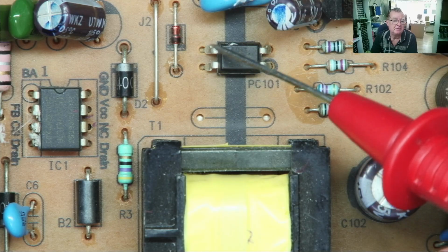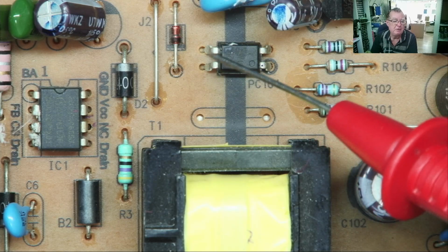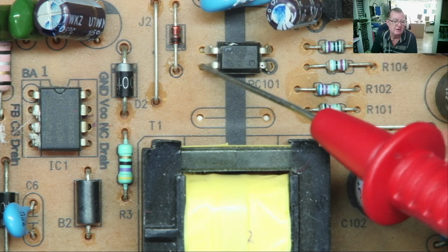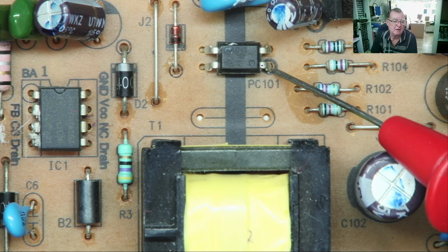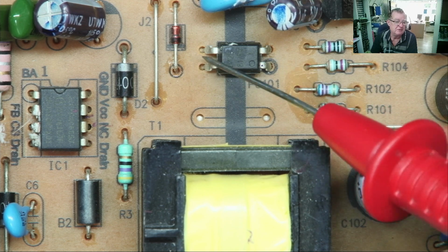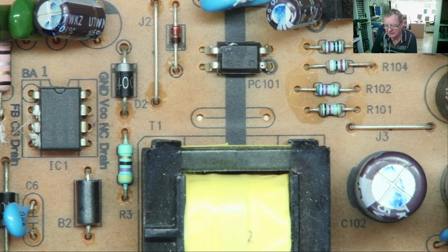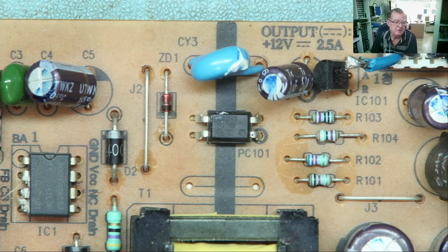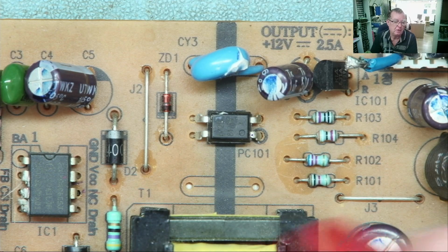The other side is a phototransistor, and if you connect a multimeter again in resistance or diode mode across here and apply your other multimeter across here to light the LED, you should see the resistance of the transistor change. That's how you basically test them, but I have made a video, all you need to know about opto isolators to fix stuff. I can link that to this one, or just Google for testing opto isolators in circuit and you'll find the basic principle.